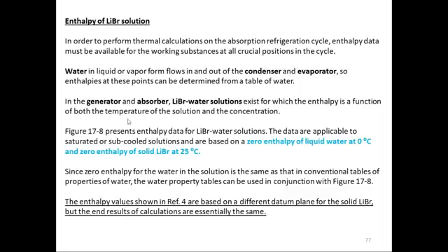So going back, figure 17-8 presents enthalpy data for lithium bromide water solution. The data are applicable to saturated or subcooled solutions and are based, this is the important thing, on a zero enthalpy of liquid water at 0 degrees centigrade and zero enthalpy of solid lithium bromide at 25 degrees centigrade. So the enthalpy chart 17-8 has been developed by giving a zero enthalpy value to water at 0 degrees centigrade and zero enthalpy to solid lithium bromide at 25 degrees centigrade. So these are the datum lines which are considered.